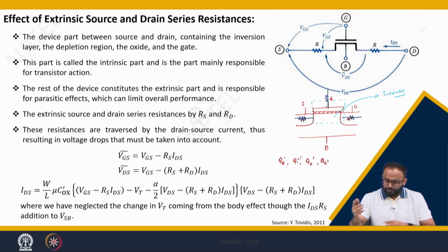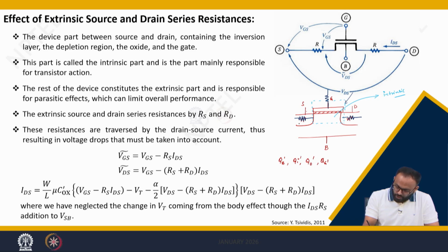Those effects will limit the operation of the MOSFET. So, you cannot say the whole MOSFET operation is captured by the intrinsic part only. This extrinsic part needs to be taken care of, and it is very important when you model these devices for high frequency applications or small signal applications. In this analysis we only considered the source resistance and the drain resistance. We are considering this analysis to be completely DC, so the gate current is 0, and if the gate current is 0, there is no drop in the gate resistance, and hence Rg is not considered.